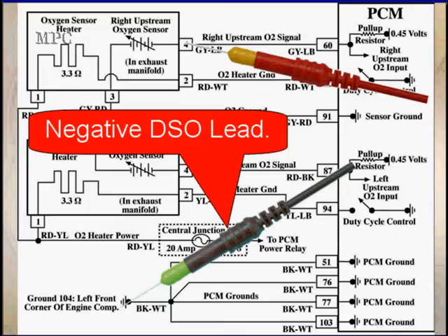Now, the most convenient ground everyone picks is chassis ground. But for oxygen sensors, let's talk about that. It's not necessarily the best ground because on this particular vehicle, the PCM is controlling ignition and fuel injectors, and we have a lot of currents switching off and on at this particular ground. We'd be much better off looking just below the red lead at pin 91 on the PCM or on pin 3 of the O2 sensor and getting sensor ground. It has less noise. You can use either one, but you will get more noise and hash if you go here, which is the common place people connect.